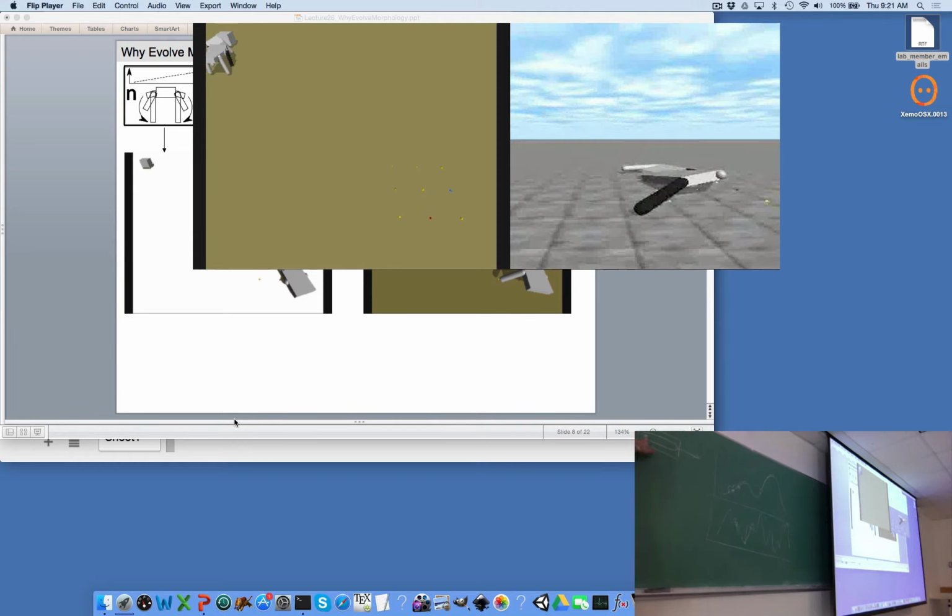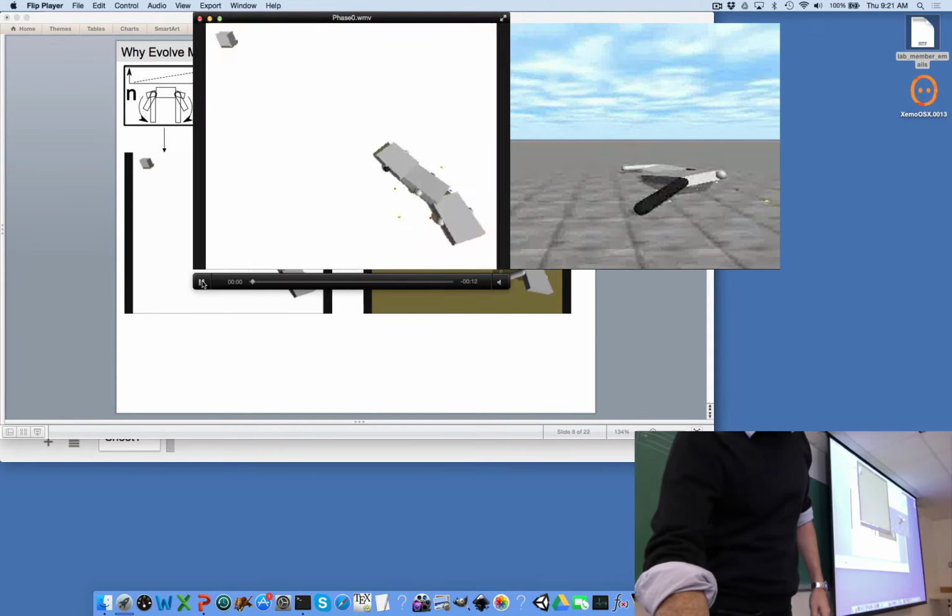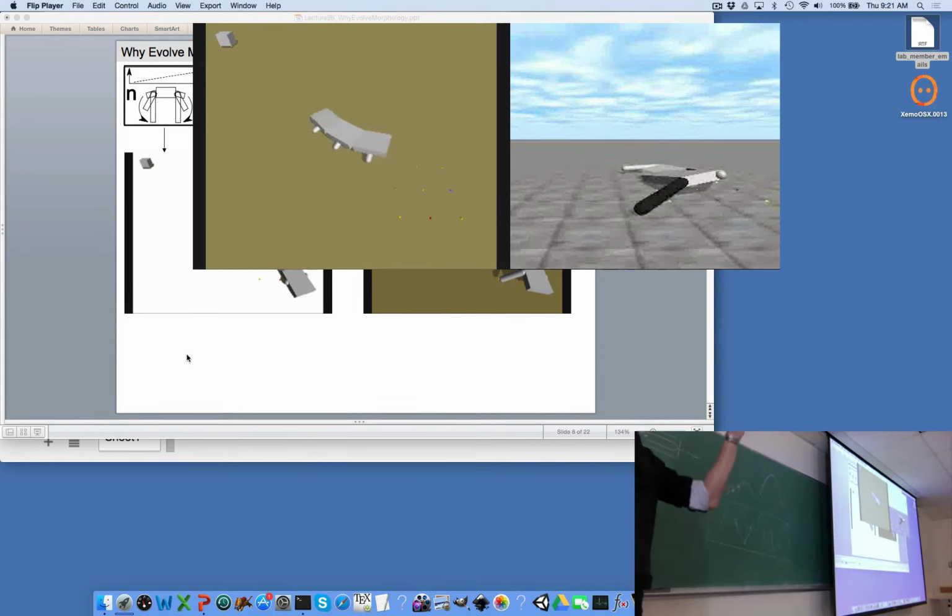The linear joint is attached to a hinge joint, and the hinge joint is attached to another hinge joint, which gives you this and this, right? So there's actually two objects, one that's being extruded right out of the right side of the body, and the other one that's being extruded left out of the left side of the body. And we use the same trick about gradually rotating the legs downward. So you can grow structure in a physics engine if you do it carefully. Yeah?